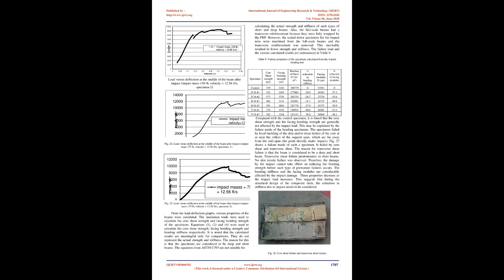As the load was increased, deflection at the center increased. Deflection was measured by means of the same LVDT, located above the midpoint of the specimen. The LVDT was connected to a data acquisition unit which gave the instantaneous displacement of the beam. The strain gauges were placed at the bottom midspan of the beam to measure the local strain of the beam. Load versus deflection plots were generated and analyzed to find the flexural properties of the beams.